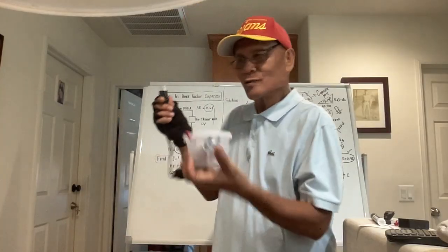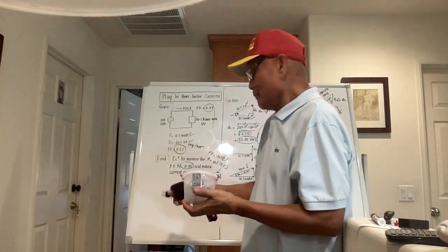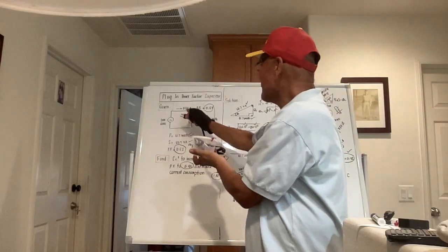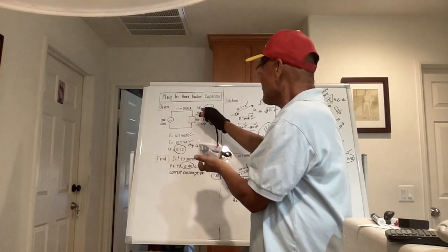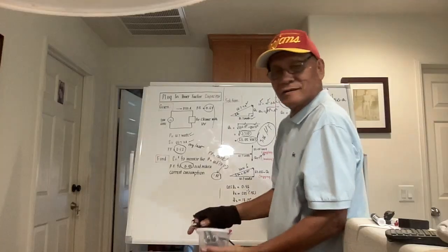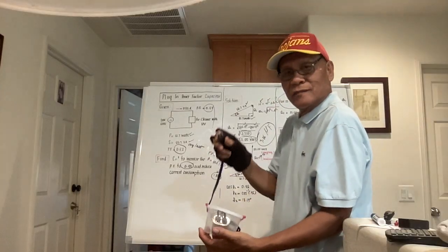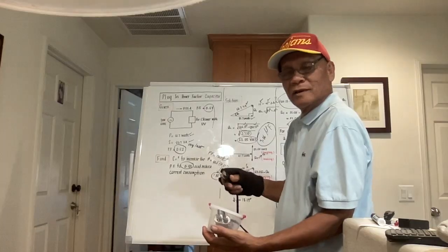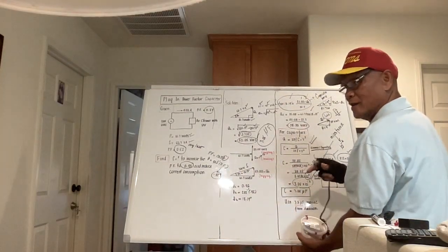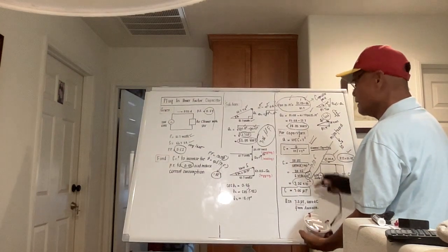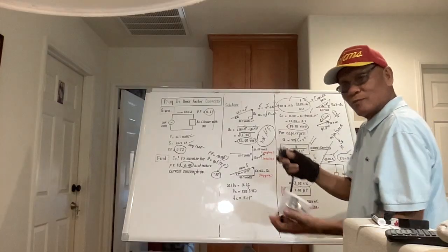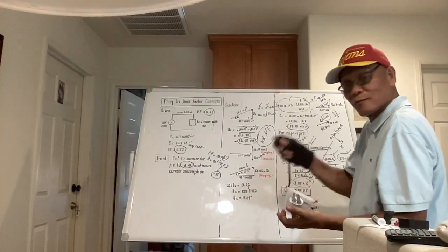So this is the one I'm using now to improve the efficiency of my air cleaner, in which the original current is 0.55 and the original power factor is 0.62. I put that in my other plug and the power factor is actually 0.92. It's not 0.95, which is what it is supposed to be if we use 7.06. Since I bought a 7.5, of course the power factor will be different, but it's very near, 0.92.